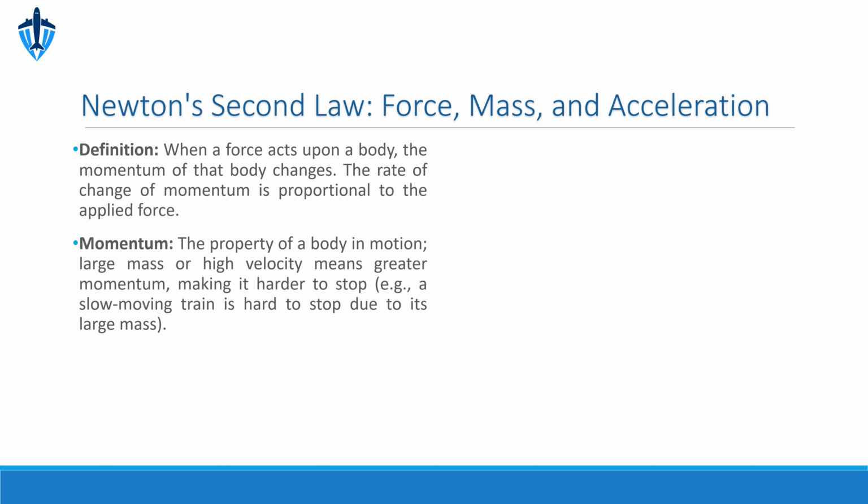If a turbojet engine moves 150 pounds of air per second and that air accelerates from 100 feet per second to 1200 feet per second, we can calculate the thrust. Plugging these values into the formula, where weight is 150 pounds, the change in velocity is 1100 FPS, 1200 minus 100, and gravity is 32.2 feet per second squared over 1 second, we find the engine generates 5,124 pounds of thrust. This directly demonstrates how the engine applies force to accelerate the air.